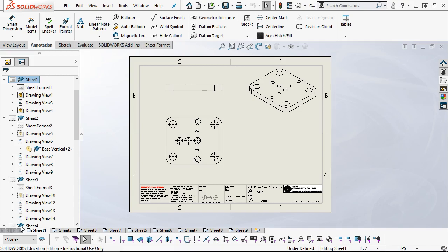So the focus is still on being able to analyze and pick out critical dimensions. Even on each of these sheets, the recommendation for this assignment for the CAM follower would be to pick some basic baseline or ordinate datums, dimension as needed, and then decide which ones are critical.